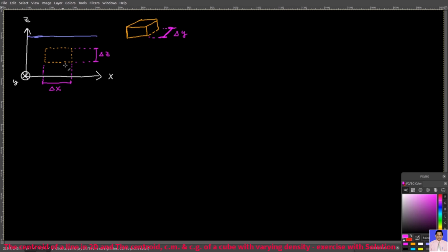This dotted line, this cuboid, is our imaginary volume. On top of this volume, you have pressure 1. On the bottom of this volume, you have pressure 2. This cuboid also has a force of gravity. Since this cuboid is in equilibrium, we can write the equilibrium equations for it in the z direction. And so the sum of the forces in the z direction would be 0.